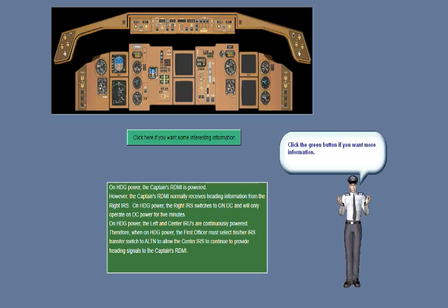When the second engine is started, the bus tie breaker of the side powered by that engine generator opens automatically to isolate that side from the APU generator to prevent paralleling of two power sources. The APU generator has been automatically removed from both AC systems. However, it remains as a backup power source in the event of a failure of an engine-driven generator. When the APU shuts down, the APU generator is no longer available.